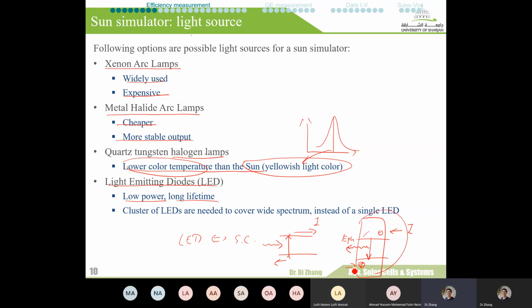If you see from the plot here how much energy we are losing for this specific LED, for this specific semiconductor, the amount of energy released is precisely the same. It is fixed to a single value. Ideally speaking, like a solar cell, if you have one recombination happening, you release one photon, and the band gap energy is translated into the photon completely. If you define the band gap energy, then the wavelength that you calculate from it is going to be a fixed wavelength.